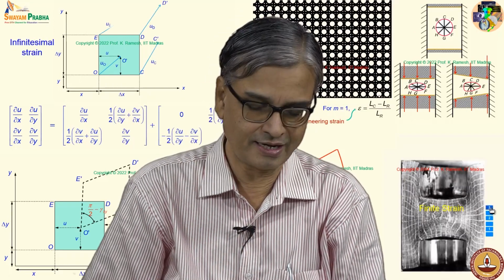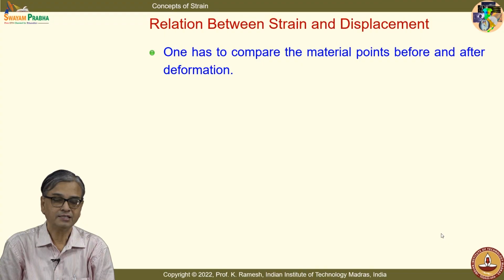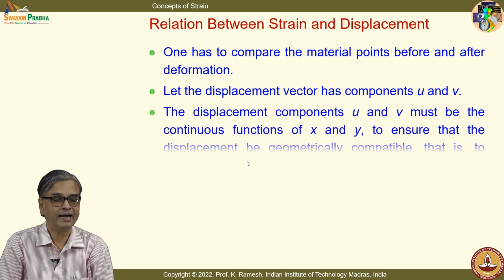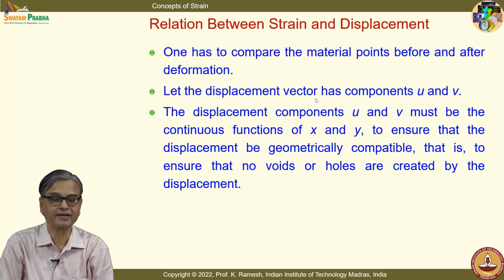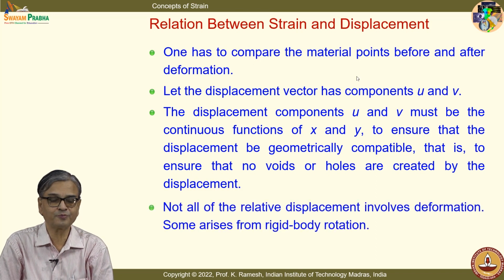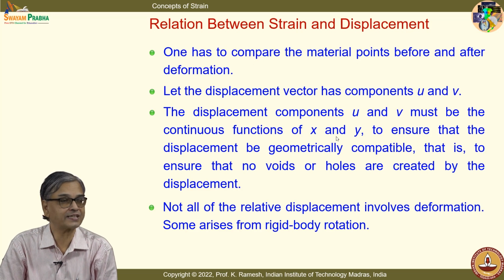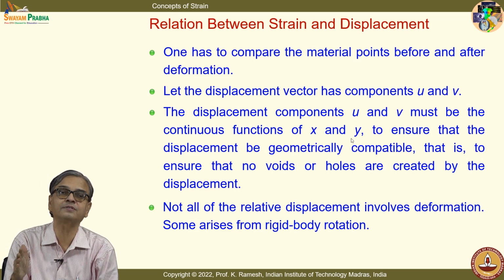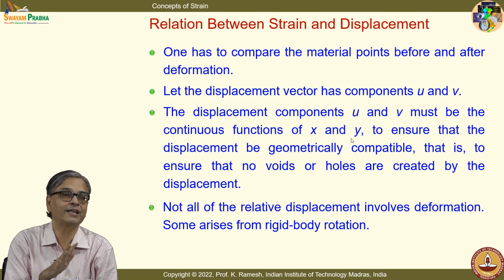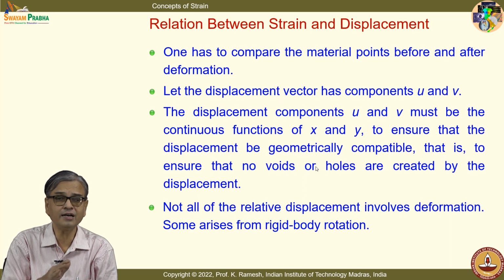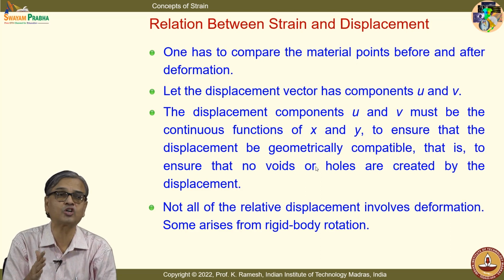We will also look at it from a displacement perspective. We have to look at what happens before deformation and after deformation, and let that be dictated by a displacement vector. When we look at a planar situation, it has components u and v. And how should the displacement components be? They should be continuous functions of x and y, so that when the material deforms, I do not have voids, I do not have separation, I have compatibility in the deformation. All that is taken care of. And you will also have to look at the fact that it is not always the relative displacement that causes strain.